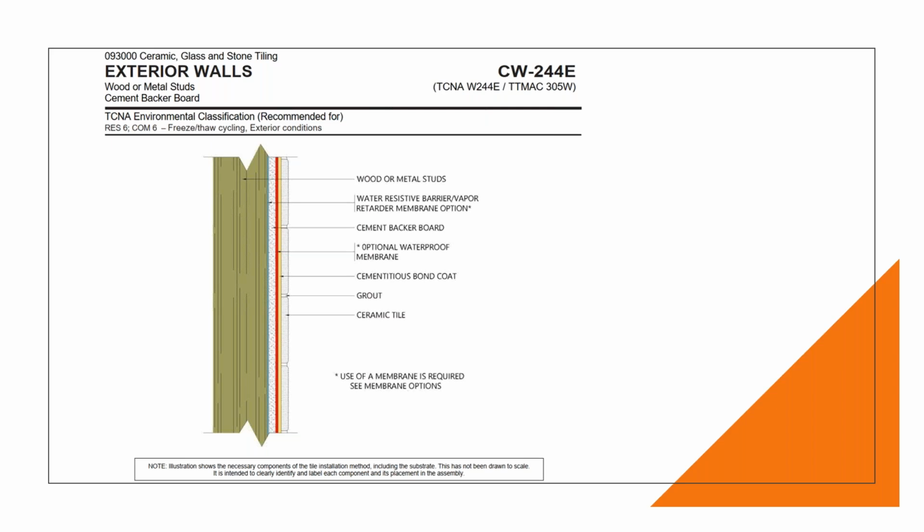The optional waterproofing membrane is here again an advisory thing to allow moisture not to penetrate into those studs, particularly if it's a wood stud, which can cause deterioration over a long period of time. And again, flashing is imperative, the proper flashing at the top and a proper exit for the moisture at the bottom of the design. Very, very important considerations.